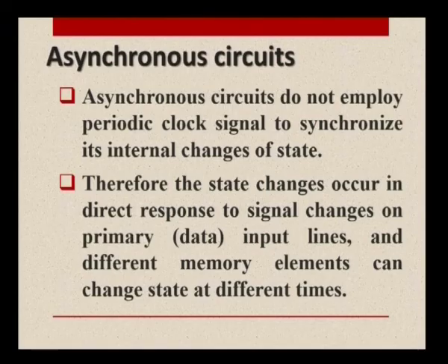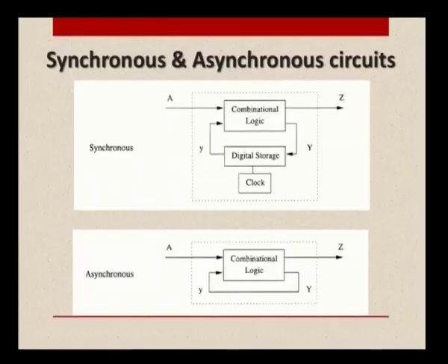Here the memory elements are the ones which store the data. So, let us have a quick look at the diagram which represents the synchronous and asynchronous circuits. So, this typically tells what they mean. A synchronous circuit is the one which is controlled by the external clock which produces pulses, and in the case of asynchronous we do not have an external clock to control it.